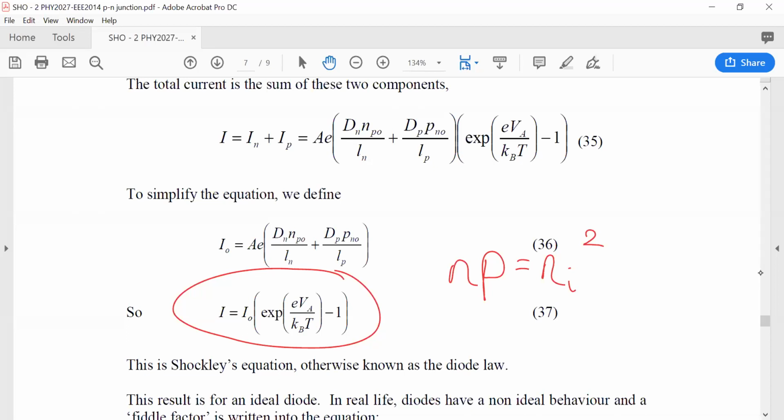But most importantly, remember that the drift current, which dominates the current flow for majority carriers, is only really balancing out the diffusion current on the other side of the junction. So in PN junctions, it's the diffusion current that needs to be calculated. So understanding and calculating the minority carrier equations and calculations is really paramount.